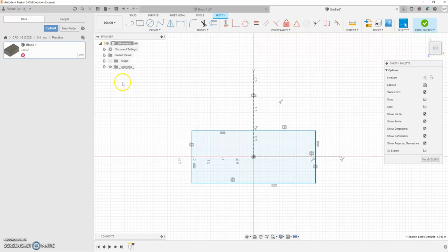Okay, so now one double check that I want you to do is to make sure that we defaulted to inches on this. If we didn't, we need to change that. Go up above to your document settings and click the open arrow. Units should be inches. What units are you in? Everybody inches? If you're not in inches, remember, click on it there, change it to inches, and check the box that says set as default. We're going to hope that that works over all your drawings. I'm not 100% positive it will.